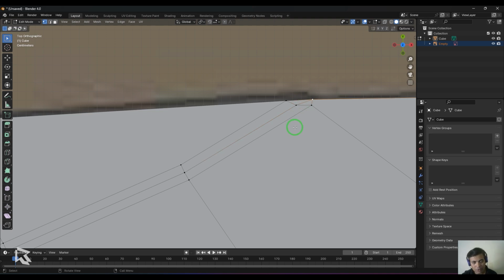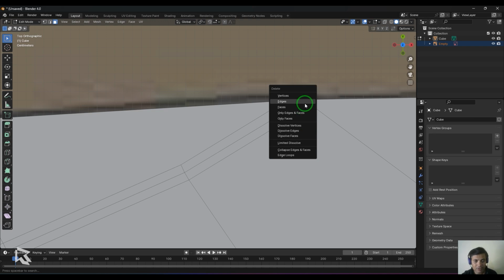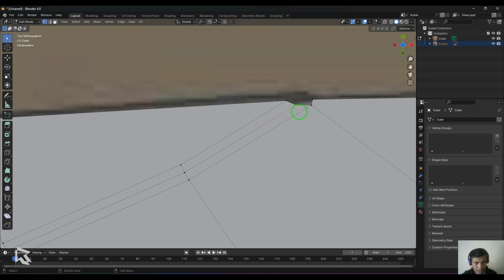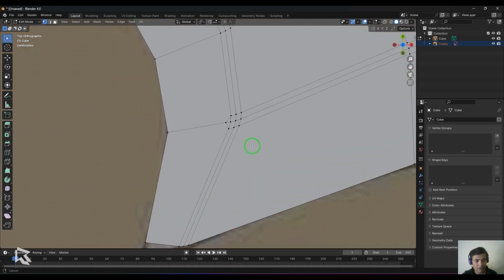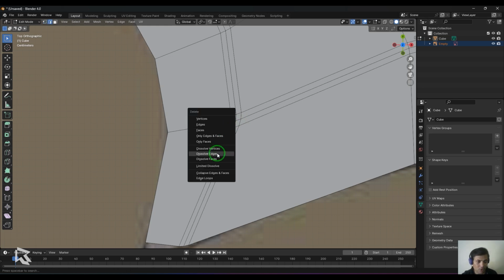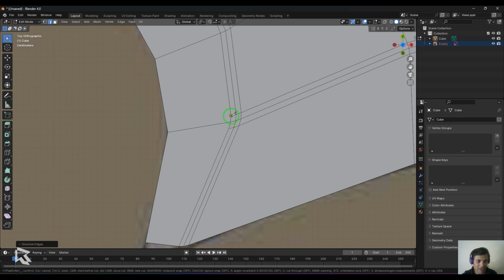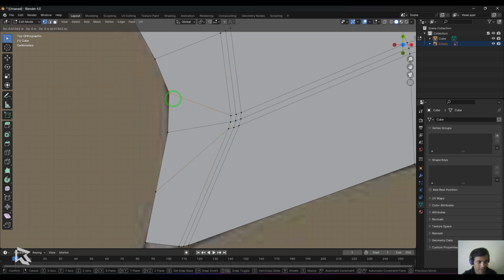Now before I fix those points, let me just select these points, delete the faces, and those points are gone. And then I select those points and then fix it like that. So yeah, here as you could see, there's some issue again. I should have extended it all the way down. So I use the dissolve edges tool, press K for bringing the knife tool, and then add those lines forward. And I'm just adding it more far, and then select those lines and then start tracing the outline like that.